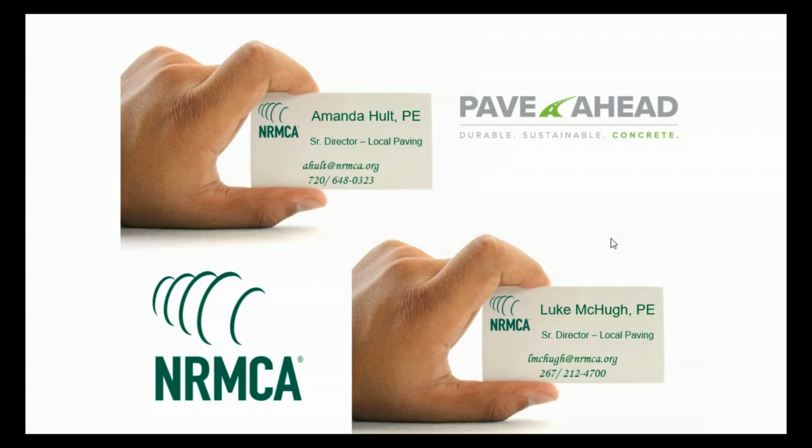But Brian and you and maybe even Luke have more experience on this, but from my experience, my knowledge, the majority of the roller compacted projects that I know of have not been jointed. So the Army Corps of Engineers, that typically uses a lot of RCC, they don't normally joint theirs.